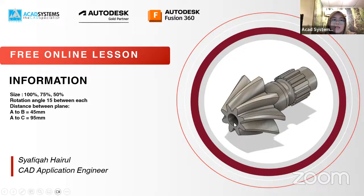The rotation angle between each of these is 15 degrees. The distance from this point to this point will be 45 millimeters, and from this point to this point will be 95 millimeters.